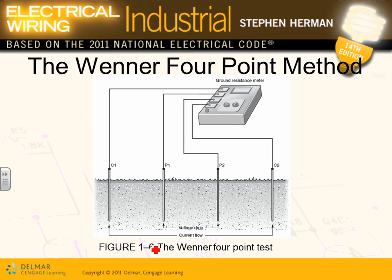So here's the first one, guys. This is the Wenner 4-point. What they do, they have a machine like this, and it pumps current into this area, into these two. These are rods. They place them away from each other. All these are lined up. They send current from this machine in here, and then they measure the voltage here. It's a machine that has 4 wires coming out of it, and shoots current into these rods.